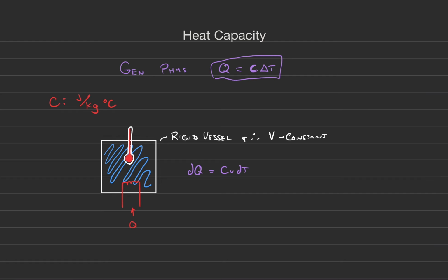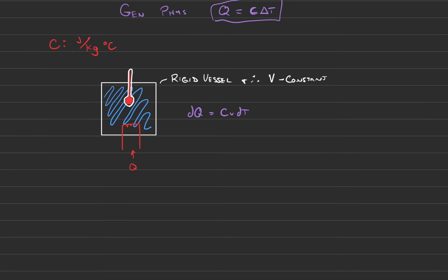So, what else do we know about the system? Well, if we do a heat balance on the system, and let's do one rigorously just because it's been a while since we've looked at heat balances, we know that the change in total internal energy of the system with respect to time is going to be equal to the negative change in the mass flow rate times the enthalpy plus kinetic energy plus the potential energy, plus the amount of Q coming into the system plus the amount of work being done on the system.